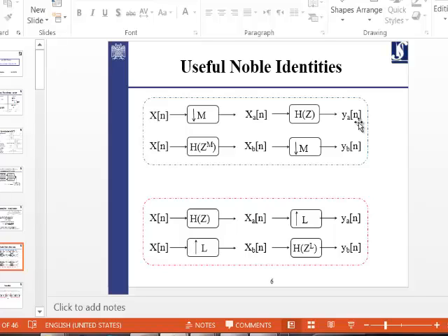Assume the second line, the signal is given to such kind of filter, and then you're doing the downsampling. The result is the same. You're in the Z domain. The Z domain behaves just like the Fourier domain, multiplication. And it means that this system with that downsampling will be multiplied. Can you write down the function for this, like 1 plus 2z to the power minus 2? The function for this one